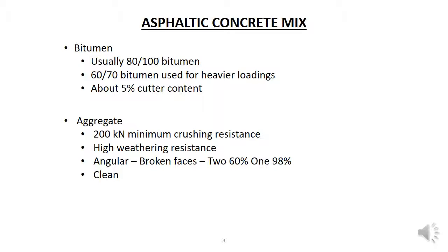The aggregate has much the same requirements as that for chip seal, in that it needs to have a high crushing resistance, weathering and abrasion resistance, and be angular in shape. Asphaltic concrete aggregate grading varies across the different mixes.